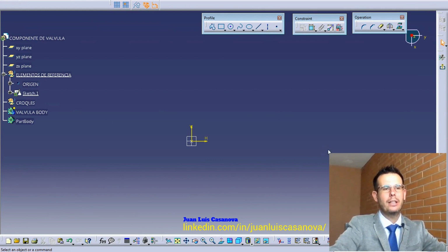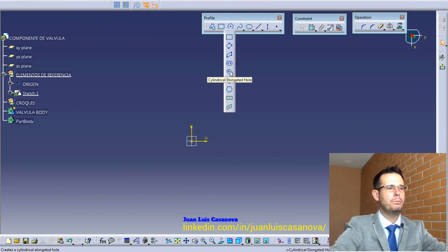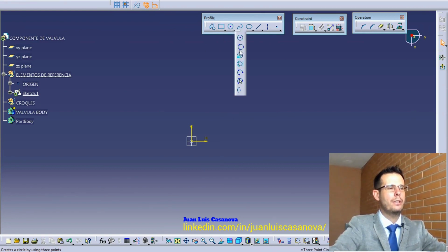All this that we see here is the XY plane, and this icon is one of the most important and most basic, which is exit. If I click here, we leave our sketch and go back to 3 dimensions. Here we have the most used Sketcher toolbars, which are the profiles used to draw our figure. Here we can draw a profile, which are lines and arcs, followed by rectangles and different types of rectangles, and even circles or arcs.